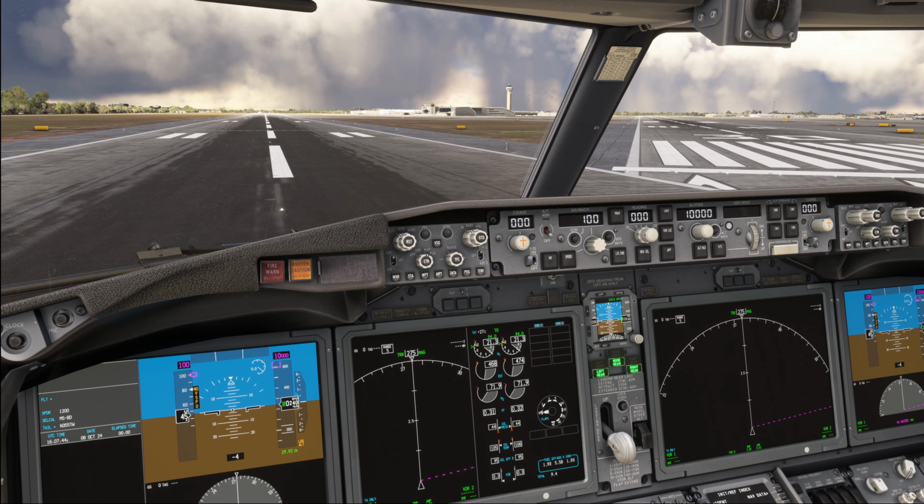When the winds, however, are greater than 58 knots total, except when setting takeoff thrust on the runway, you must limit engine thrust to idle. However, due to the high gearing ratio of the engine, minimal thrust is required to commence taxi anyway, so taxi should still be possible. A new idle thrust has also been introduced to the engine, and that is icing idle.